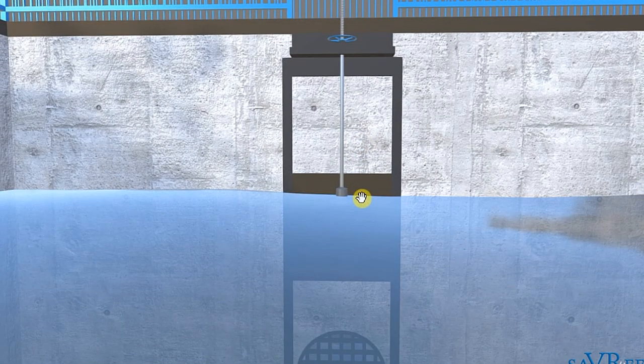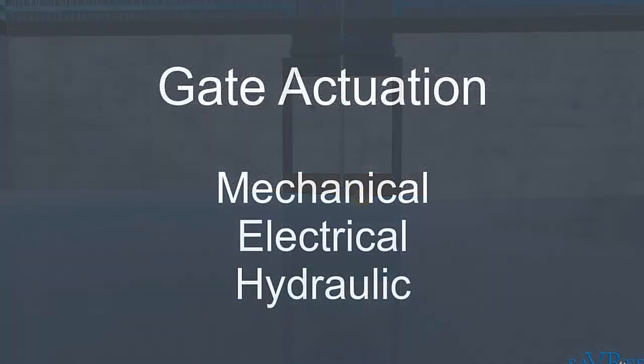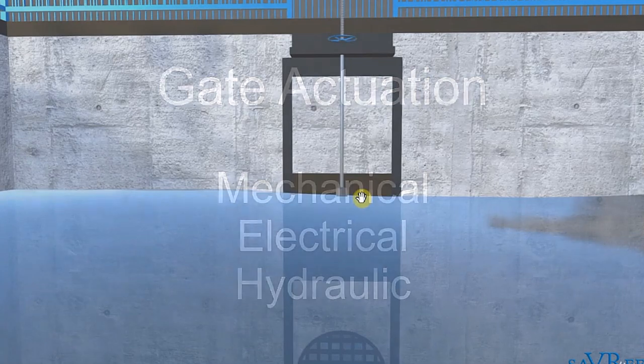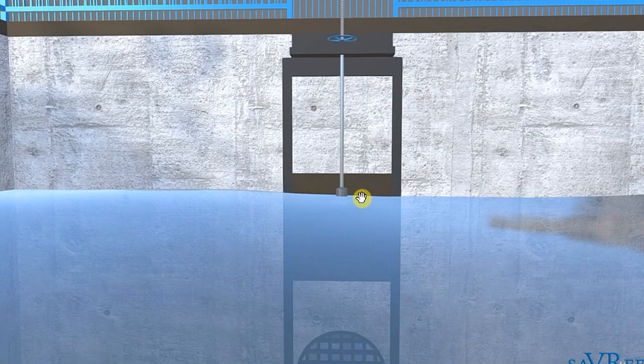Generally, gates are going to be mechanically actuated, that is to say by hand, electrically actuated using a 3-phase motor normally, or perhaps a single-phase motor, relying on DC power in an emergency, or hydraulically actuated, and we'll use hydraulic oil pressure and a hydraulic cylinder to lower and raise the gate. In normal operation, you can use things like AC motors and also hydraulic pistons.